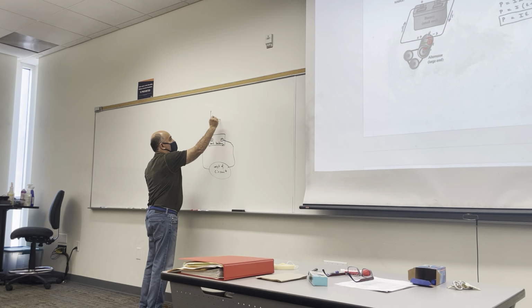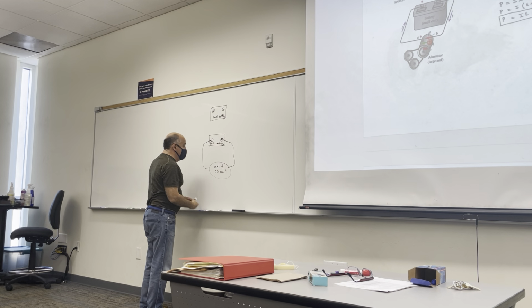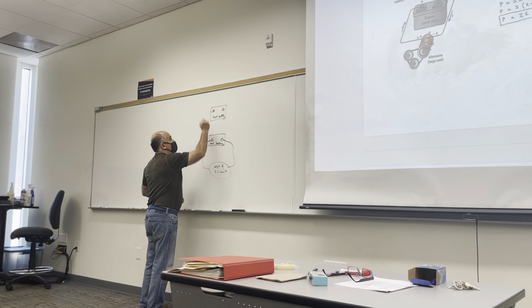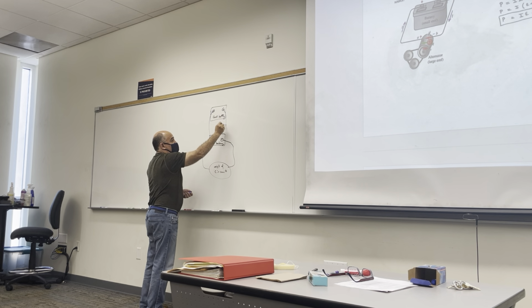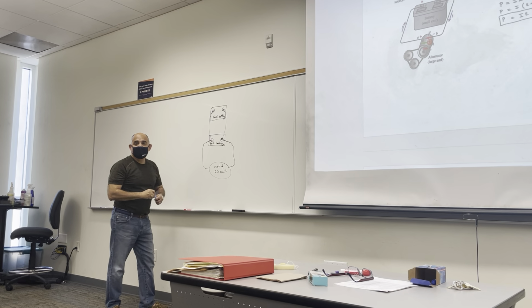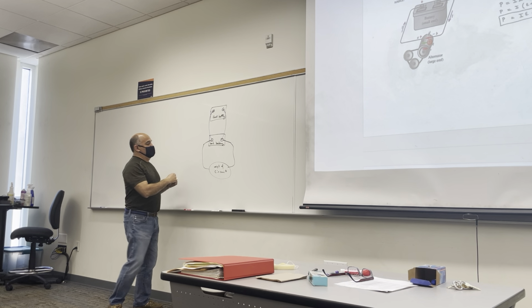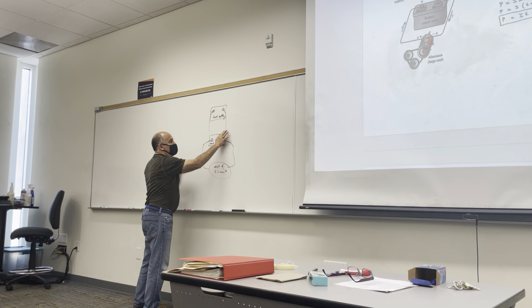So what you want to do is you want to bring a good battery, right? And this is the plus, and this is the minus, and you want to connect the plus of this to the plus of that, essentially to replace that one, and the minus of this to the minus of that. So when this connection was not made, right?